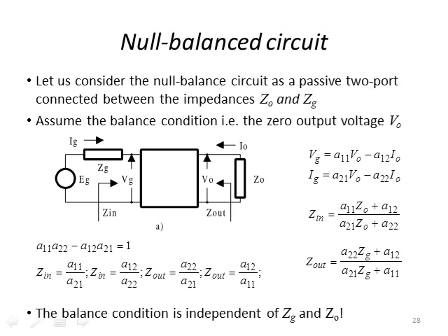Because we always have these problems associated with the load that we have to drive and the sensor configuration that provides a finite resistance or a finite current or a finite voltage drop across the sensor that always introduces some bias to our measurement. So using these null-balanced circuits, we can get rid of some of these biases.